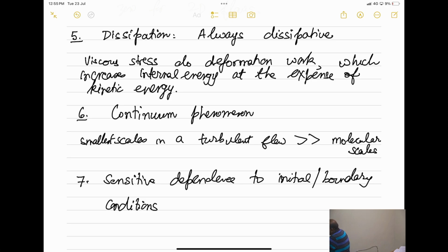Or maybe you talk of flow in a pipe, then of course, assuming that nothing has happened, the boundary condition will stay the same. But in the boundary conditions you also give the inlet condition. Inlet condition is on velocity. Given that velocity, there may be some fluctuation, there may be some epsilon variation. So pressure fluctuations could be there if they are there in the boundary conditions.